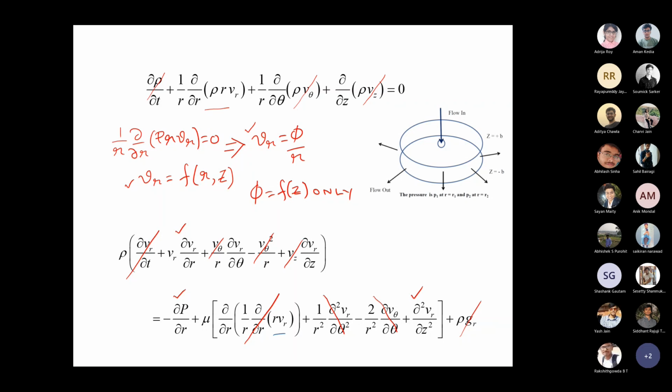So for micro scale applications, which is one of the hallmarks of microfluidic applications, the gap being small essentially dictates what kind of pressure gradient you need to apply. Those calculations of how the system size would dictate the pressure gradient required would be very important for microfluidic applications, when you can safely neglect the convective transport of momentum.